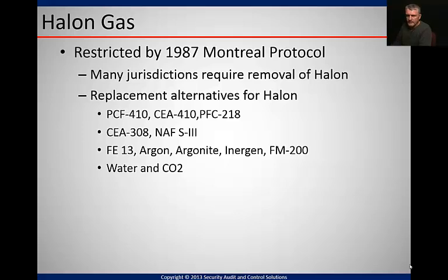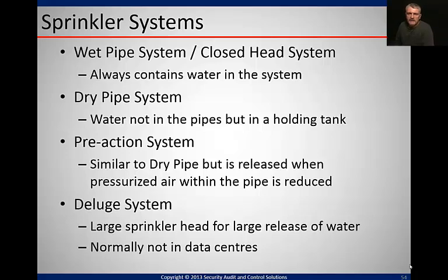The most common one is, for example, the FM200 and Inergen. Its replacements are also water and CO2. The problem with CO2 is that it replaces oxygen, and we as humans require oxygen, and that becomes a threat to humans.